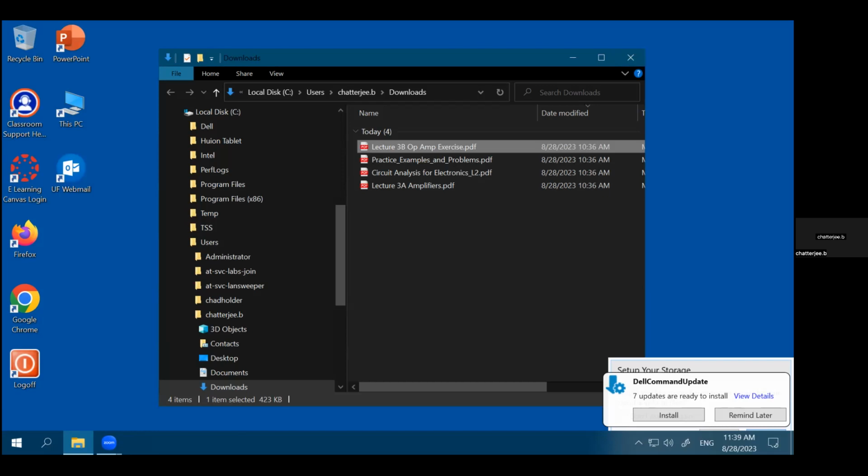Now, input can be like this: the small signal AC. The output is a large signal AC. Small signal means the input is small. Large signal means that it is large. That's as simple as that. Now, the important thing is that we know about the swing. What should be the average? So if this is 1 millivolt, is it 1 millivolt across 500 millivolts, or is it 1 millivolt across 0 millivolts? What is this average level? Is it -1 to +1, or is it 499 to 500, if your VDD is 1 volt and ground is 0? That's the question.